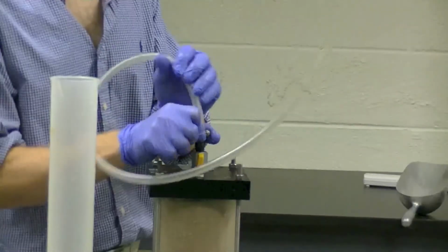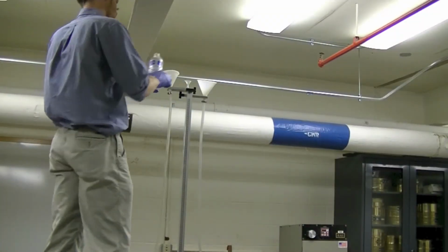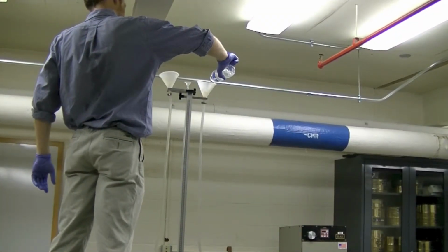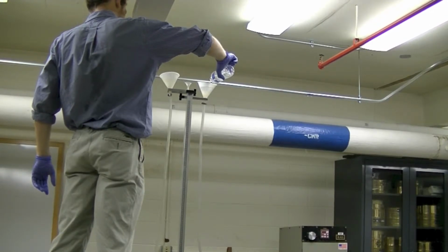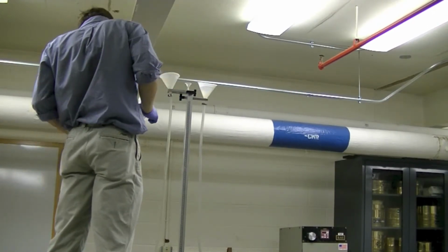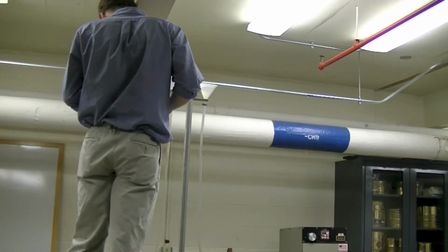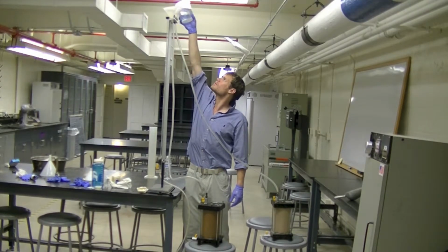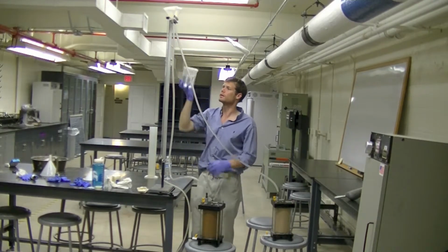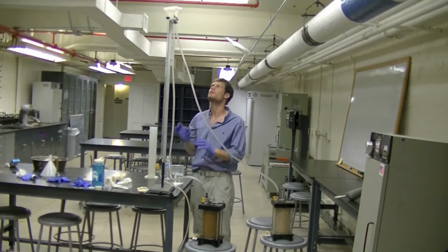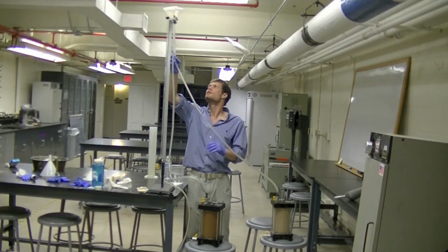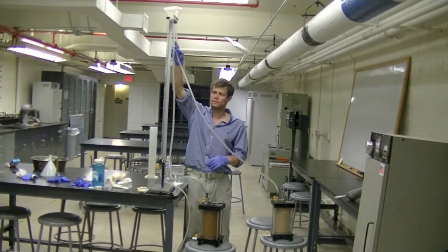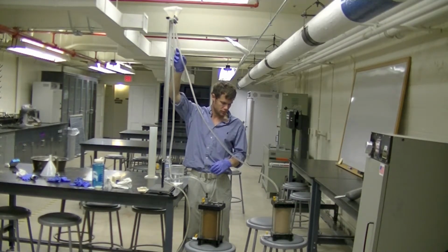The simplest way to de-air and saturate the samples is applying a constant hydraulic head over a long period of time. Close the outlet and apply a constant hydraulic head to the sample. Try and remove any air voids trapped in the tube at the time of application. Also, one can open the bleed valve on top of the permeameter if the air pockets will not migrate up the tube. The bleed valve forces air and water out of the top of the permeameter. Once there is no change in hydraulic head with time and no air pockets are noticed, the sample is fully saturated and the test is ready to begin.